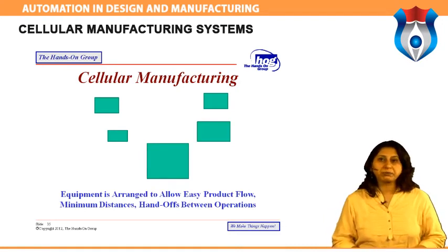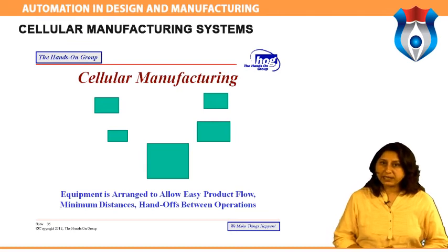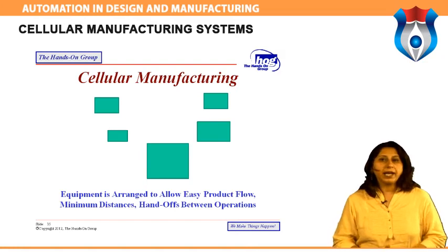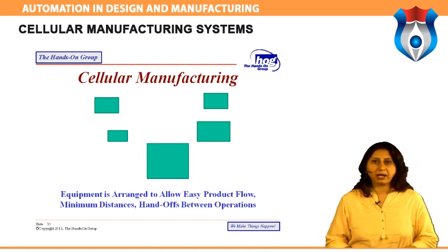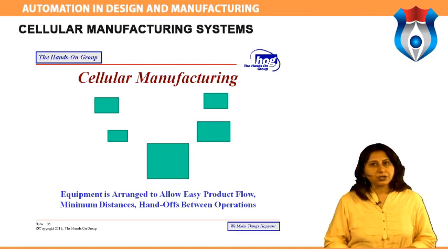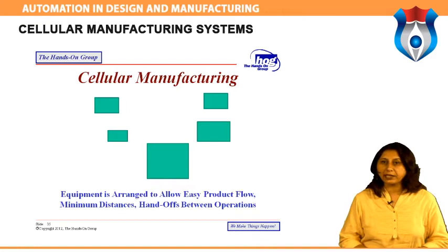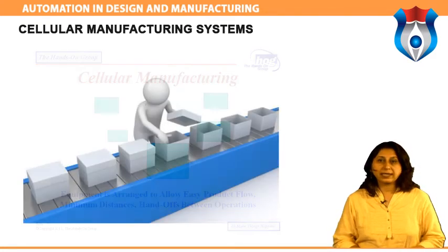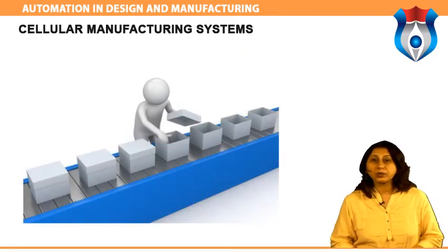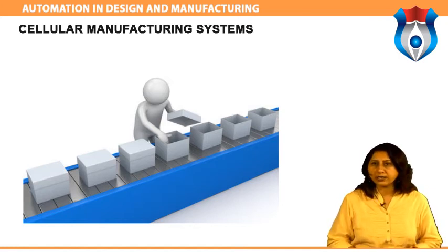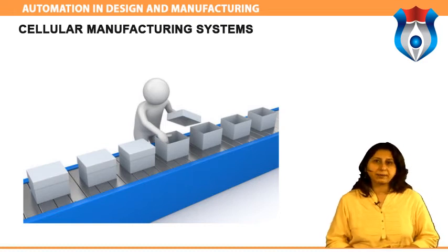Cellular manufacturing can provide companies with the flexibility to vary product type or features on the production line in response to specific customer demands. The approach seeks to minimize the time it takes for a single product to flow through the entire production process. This one-piece flow method includes specific analytical techniques for assessing current operations and designing a new cell-based manufacturing layout that will shorten cycle times and changeover times.